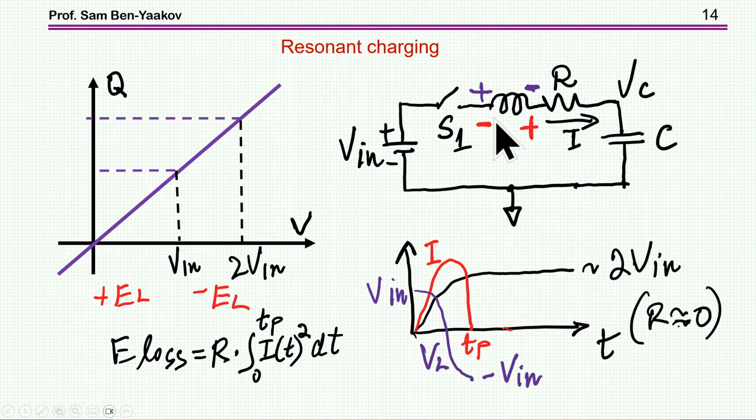At this point, the stored energy in the inductor is now being restored or harvested, you might say. There's no problem for the inductor to change polarity, and now the current goes this way, continuing. It is delivering energy to the capacitor from the inductor and also from V in. Okay? Both are adding this energy, and theoretically the voltage here will be twice the input voltage. Well, you can figure it out by writing differential equations, etc., but this is really what's happening in the physical sense.